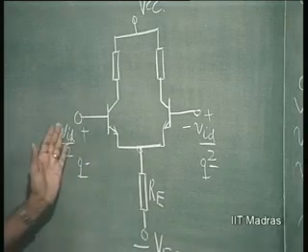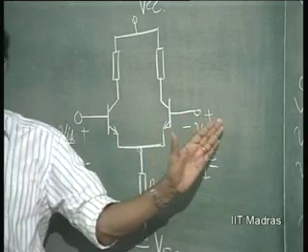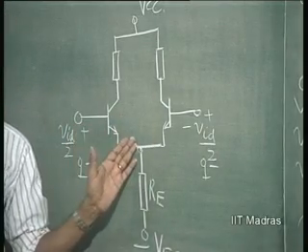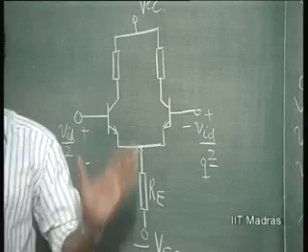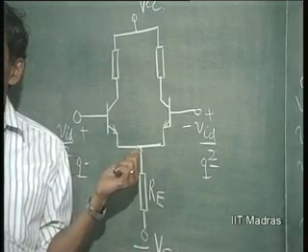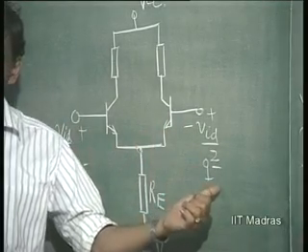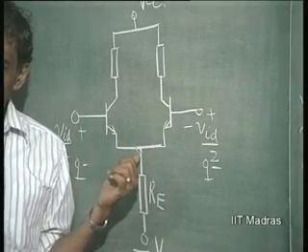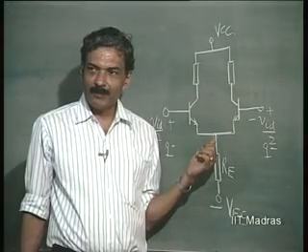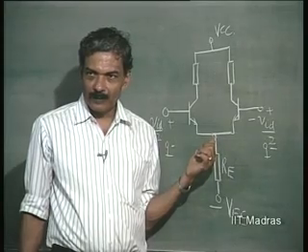So, the effective voltage change here, if you apply positive at one end and negative at the other end to any symmetric circuit, corresponding to a common point here, is going to be 0. That means this will remain at the same state at which it was originally existing without having anything applied at all. That means this will remain at the quiescent state. Is this clear? This is the property of a symmetric circuit that we are going to use.